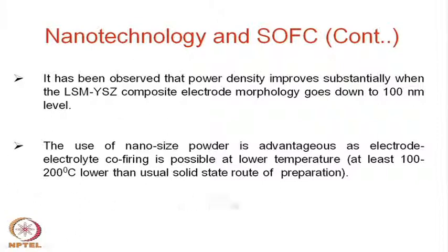If you remember, there is a co-firing technique for the anode supported fuel cells, where both the anode as well as the electrolyte are co-fired at the same temperature, where we expect that the anode should be porous and the electrolyte should be a completely dense material. So, co-firing has a very important role in fabrication of SOFCs. If you can reduce the co-firing temperature by 100 to 200 degrees, that certainly improves the total process and facilitates our fabrication technology.